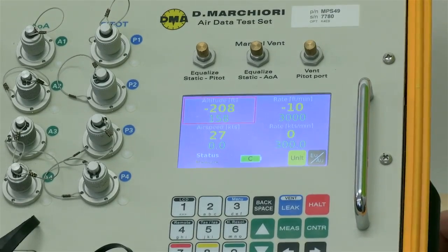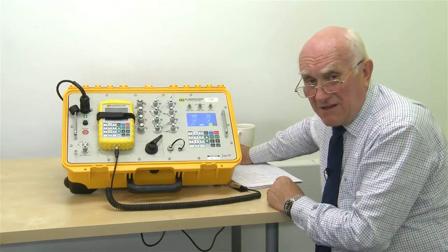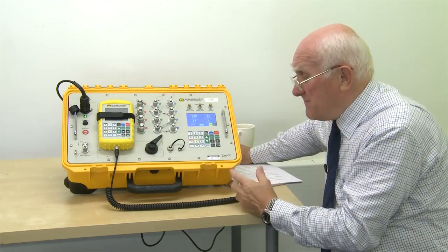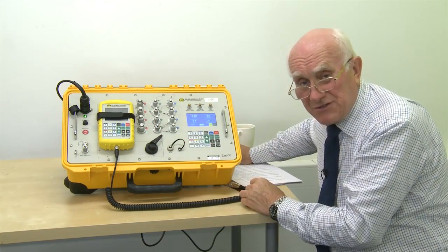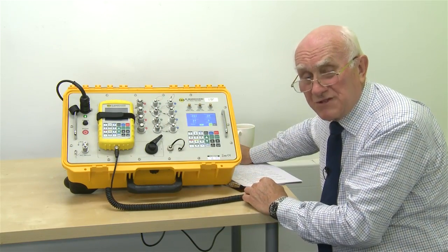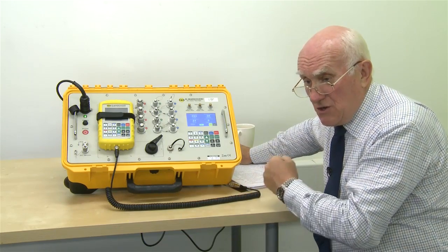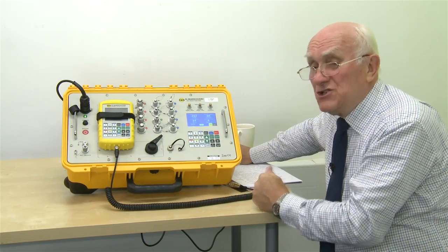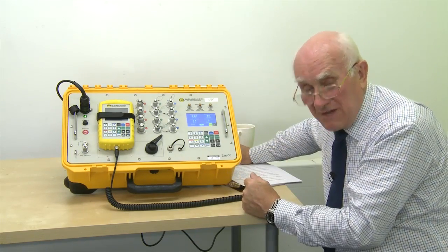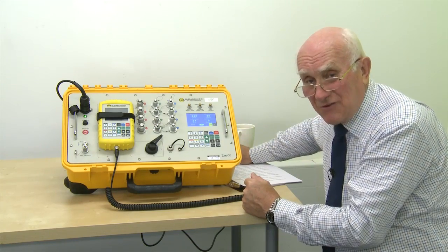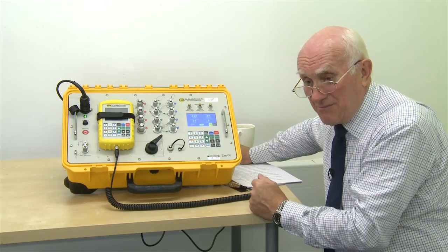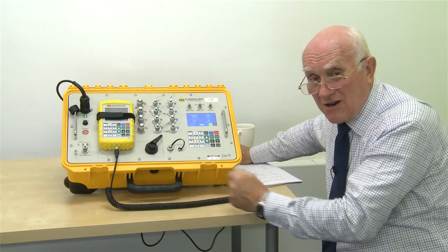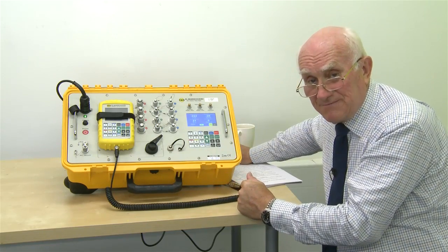We move on then to the top. They're the manual letdown valves. Generally speaking, they're probably never going to be used because the instrument comes with the capability to run on internal batteries, and the batteries will give you 2 hours of operation. This means that you can use the instrument if you wish away from AC supplies, and in addition, should you actually lose the power in the middle of a test, you won't see any difference. The power supply will take over and make everything safe, and that includes taking the test set and the aircraft down to safe ground levels.